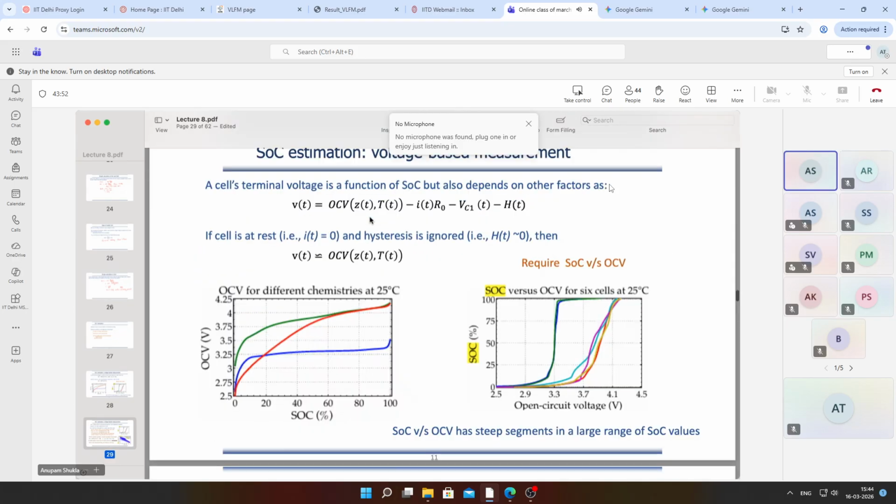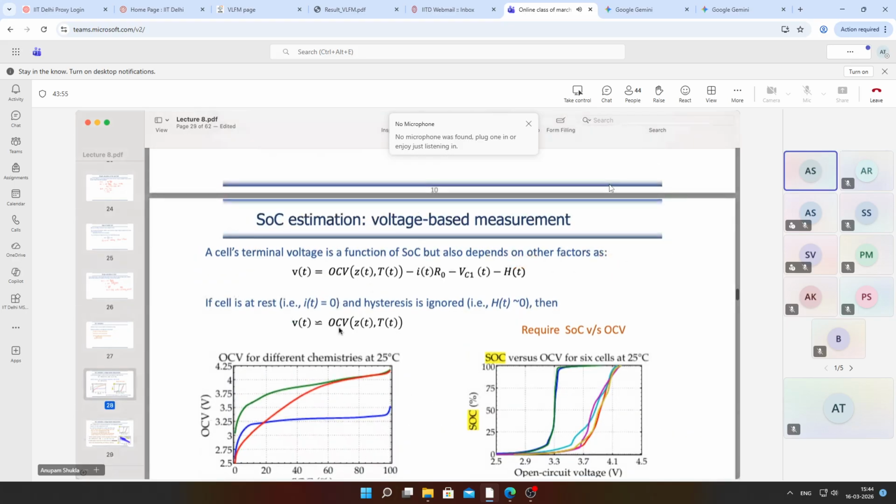So if we go back to this equation and say that this is not good enough, especially when we flip the graph to represent the situation that voltage measurement is now the independent variable and SOC is dependent, then we have to go back to this equation and see which one of the parameters is easily determinable. And we find that this is quite reasonably estimable. One can get current to good accuracy, and R0 is pretty easy to estimate.